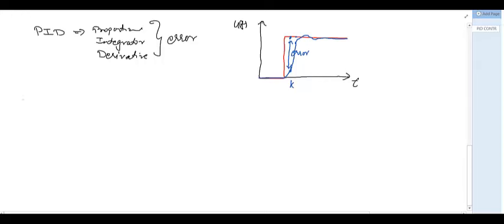So let's go over the PID formulation. Let's say we have this u(t). This is our controlling function. This is what we're going to control, and we'll have the gain of the proportional controller multiplied by the error at point k. So let me just change this t to k as well. We'll do this in discrete time with k index, and we'll add the integral controller to that.